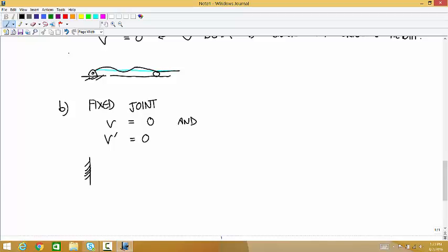So to visualize that, if the blue is your original beam, due to the loads, the beam can do all sorts of stuff out here. But right at the wall, it has to have a deflection that's equal to 0, and it has to be horizontal. It has to be its original slope. Any questions about that, or like just trying to make sense out of intuitively why that is?